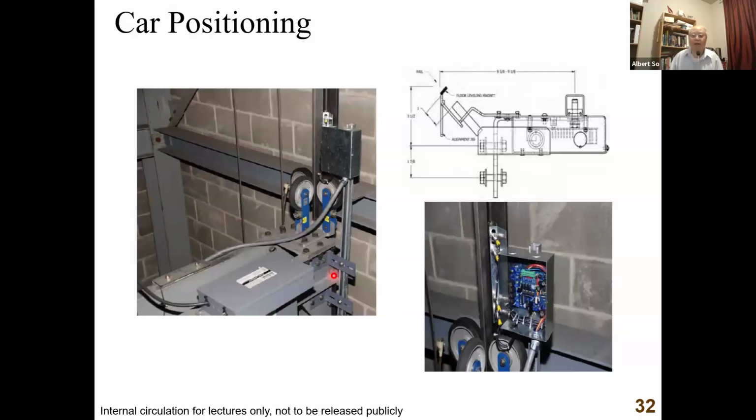That's why after power failure, the controller will have no idea where the car is. Okay, so after power failure, and then the electric power is restored back to normal, then the lift system will try to drive the car up or down, depending on the previous position of the car, and then when the car goes up and down, it will have detection again. Then the controller will know where the car is.